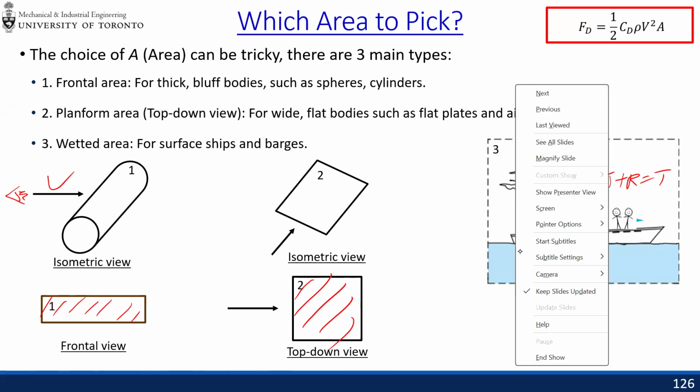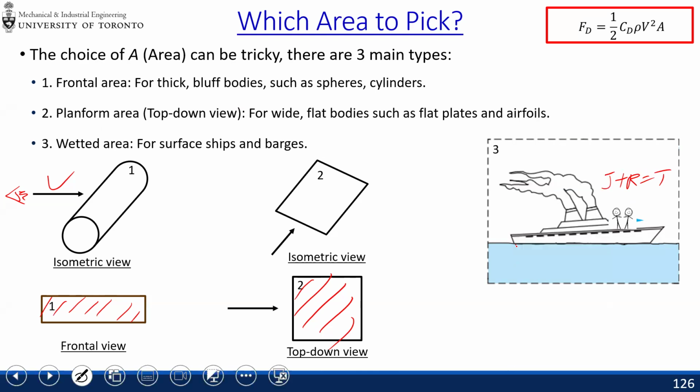So with boats, now we're actually focusing on their submerged surface area. It's called wetted area. We have a jargon. The idea is that you want to basically look at the surface area of the object below the water line. These are quite hard to calculate for real geometry like boats and barges, so this will usually be given to you as a problem at this scope. Unless you're just tracking an oil drum that's being towed along, then in that case, you can calculate the surface area of the submerged section.